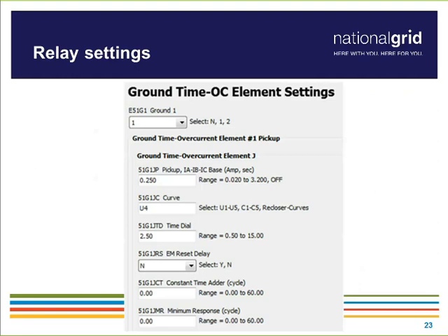You would also submit if you had a fuse service. If you were anticipating utilizing a certain fuse type, we would expect to have that fuse type listed on the drawings, as well as the fuse characteristic curves so we can review those in coordination with our system. And in addition to those types of curves and settings files, we also require on paper for you to submit your inverter settings as well. We would review those at that time to ensure that the inverter settings are in compliance with our ESPs and the IEEE required settings.